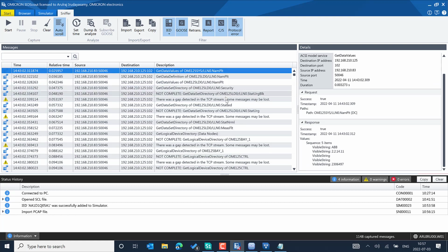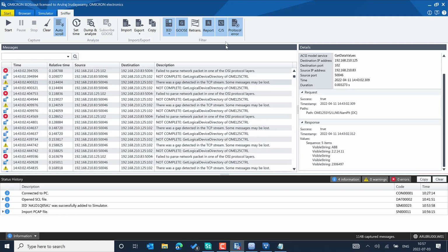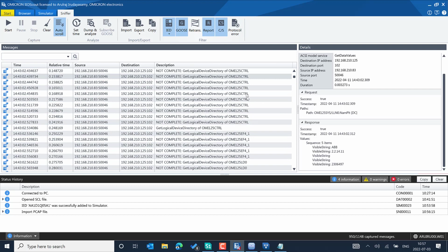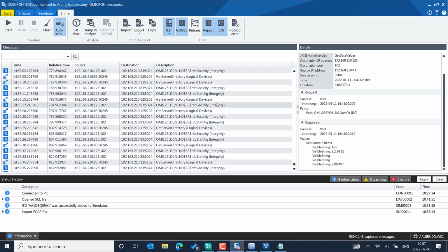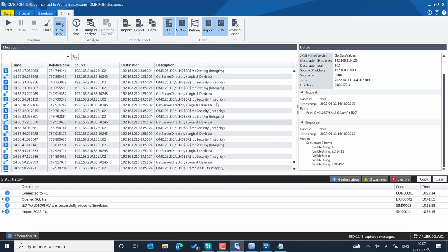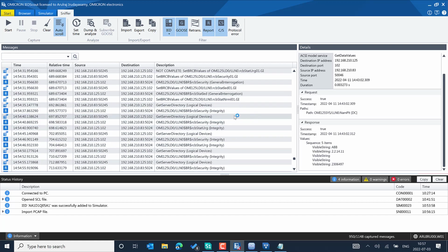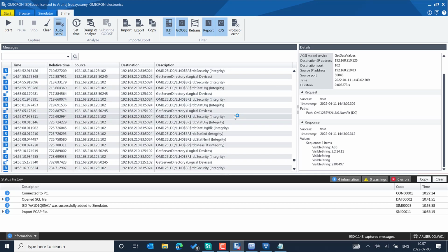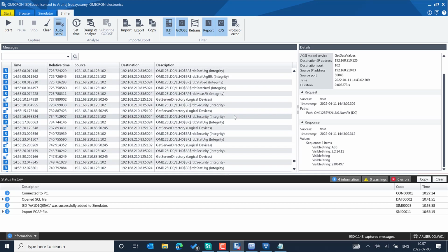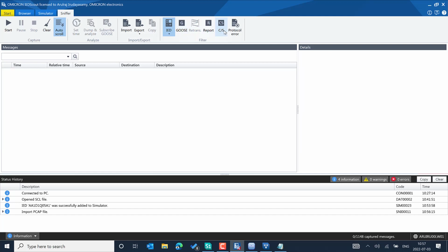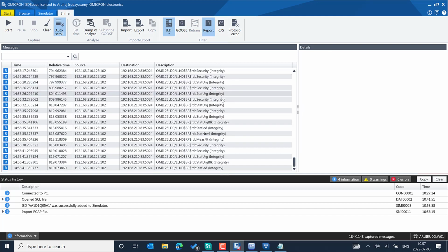There you can see the request and response very well, and you can also uncheck the protocol error to focus more on the request and response. It enables the report control block, also the trigger options, then general integration, and it goes for the data change. Based on the different trigger options, it receives the report, and you can use it for troubleshooting. You can flexibly uncheck and check the report and client-server traffic, and you can enable only the reports.